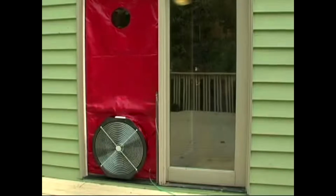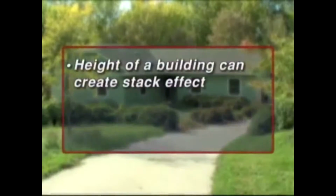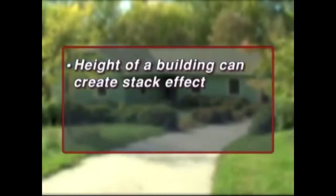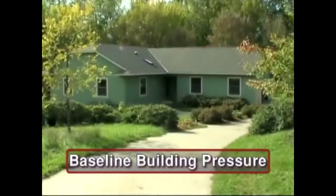When conducting a blower door test, we want to measure the change in building pressure caused by air flowing through the blower door fan. In order to measure this change accurately, we need to account for any existing pressures on the building caused by stack, wind, and other driving forces. This existing building pressure is called the baseline building pressure.